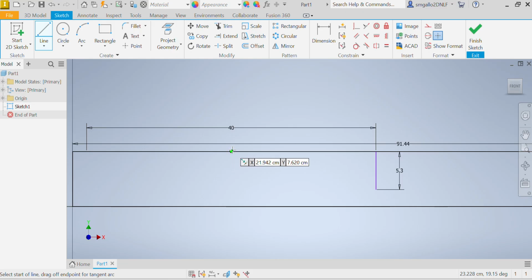I notice that as I get close to it, it is clicking into my midpoint. I will go ahead and add my root chord. My root chord going straight down at 90 degrees is 7.6. And sure enough, that takes me to the very edge of my balsa wood. Now I can go back to the right and connect to my wingtip.